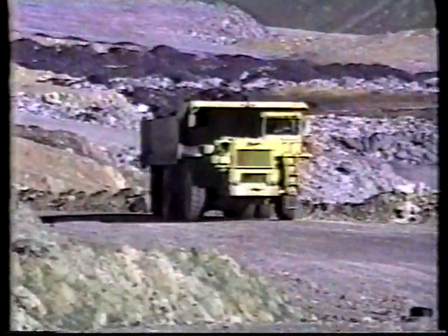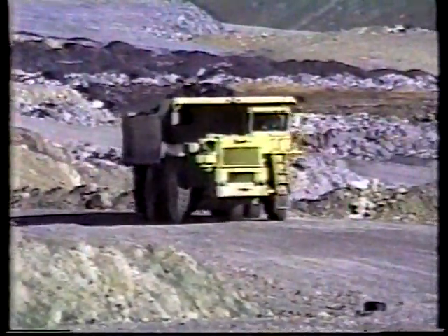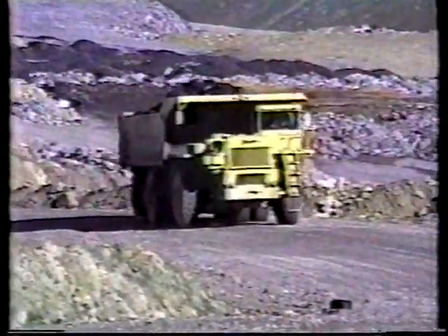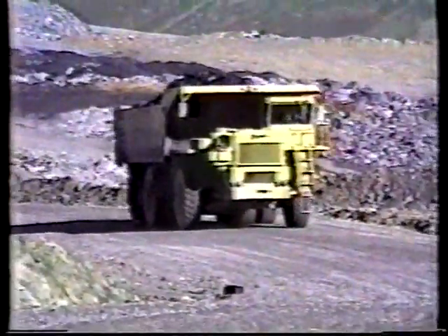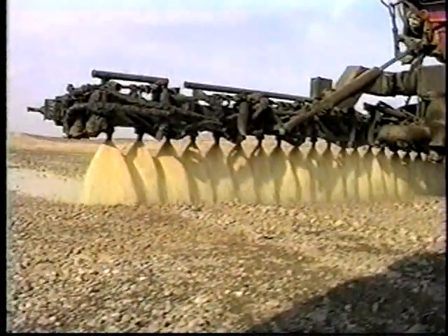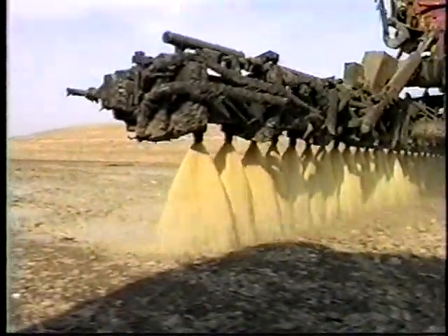Dust control, erosion control, and surface penetration treatments must resist many of the same forces as pavements. To be effective, a treatment has to endure exposure to varying degrees of sunlight, rain, wind, temperature, and moisture fluctuations, as well as foot or vehicular traffic. Bonding and sealing performance are interrelated and essential to economical, long-lasting performance in all these applications. Road oil is used for a variety of surface penetration applications, which include dust control, erosion control, prime coats, fog seals, and surface seals.